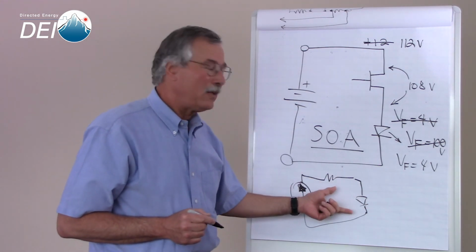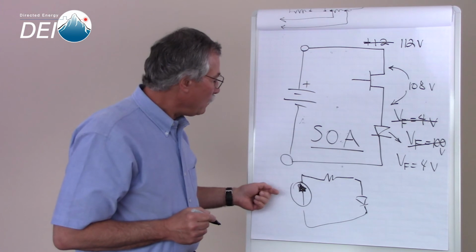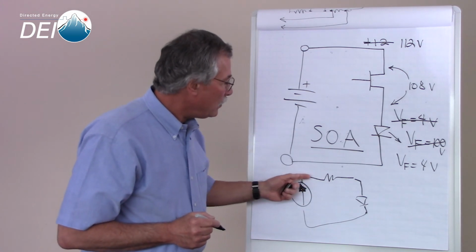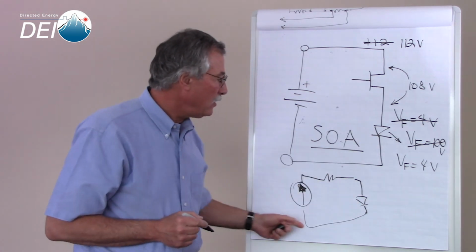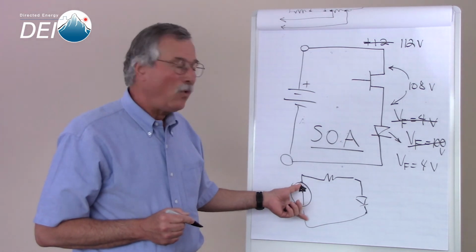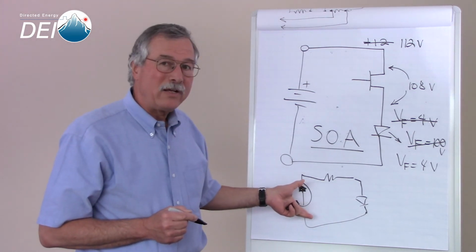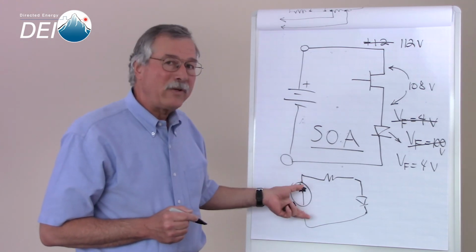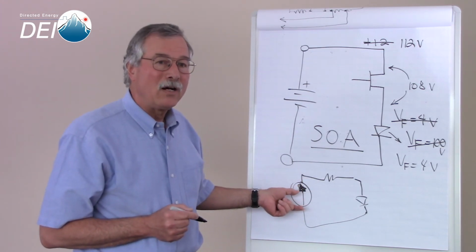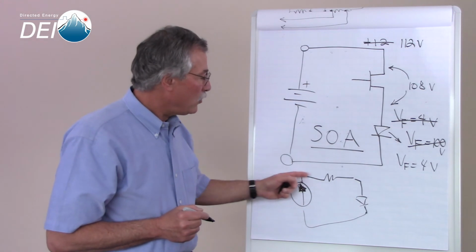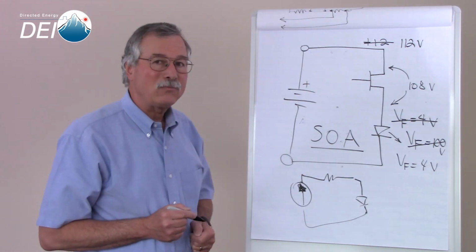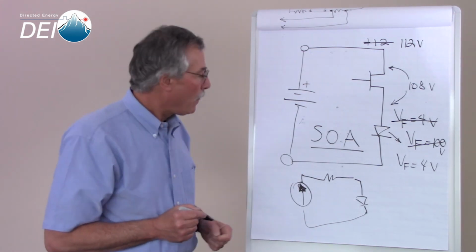When we do something like that, we very often will use strip line cable in this circuit, and it's very important that we watch the amount of inductance in that strip line circuit. So for more information on that topic, please see our webinar on making connections. It addresses this entire issue of very fast pulses and proper hookup.